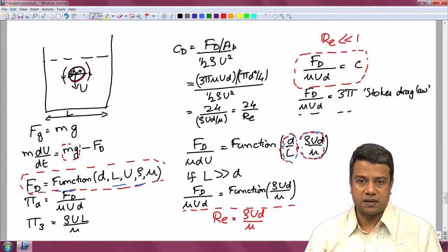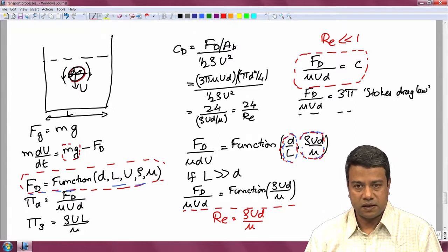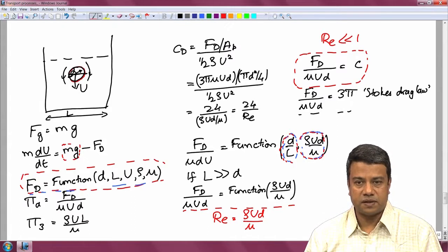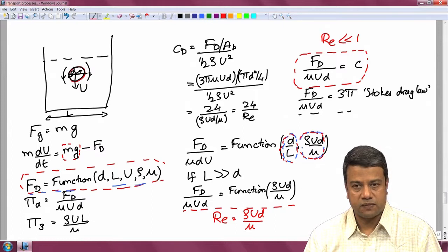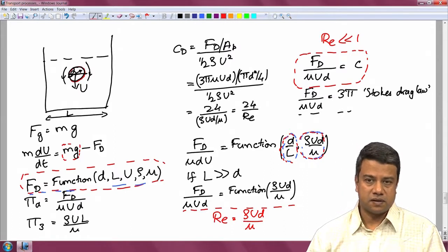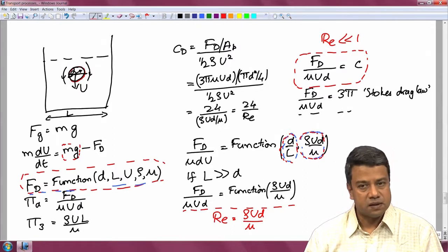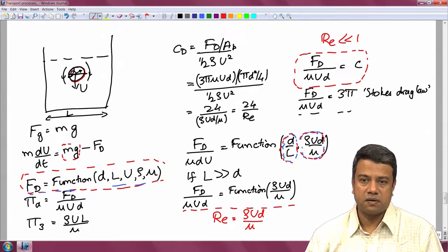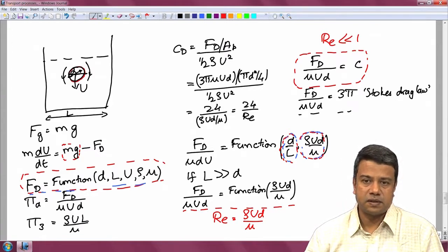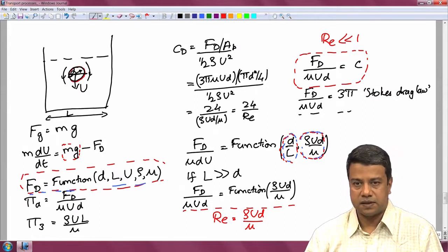And as I told you in the last lecture, even though convection can transport momentum within the fluid, ultimately at surfaces there is no convection perpendicular to the surface, and therefore ultimately the momentum has to be transported due to diffusion alone. So when the convection is much faster than the diffusion, it is not always possible to neglect diffusion. That is a point that we will come to a little later. You may need to consider diffusion within thin regions close to the surface. So that is the summary of the dimensional analysis that we had done in the previous lecture.